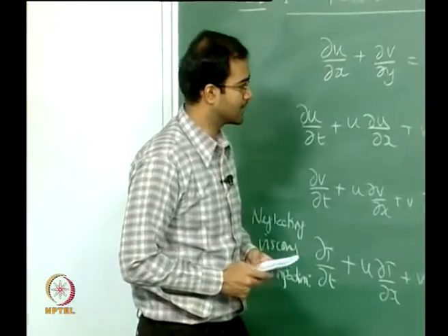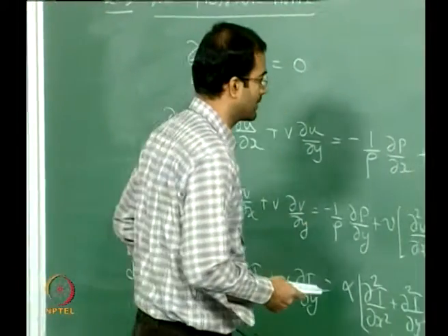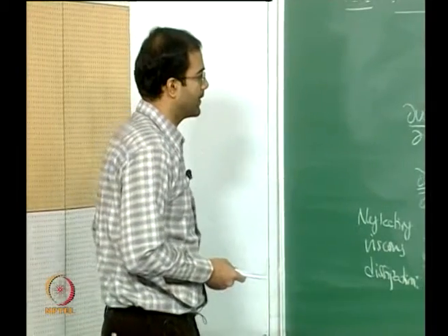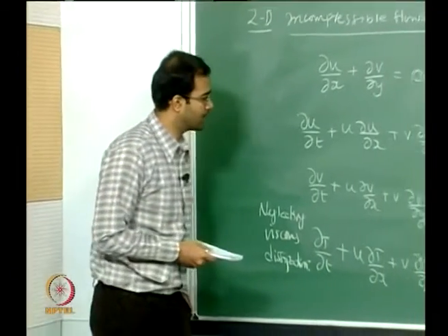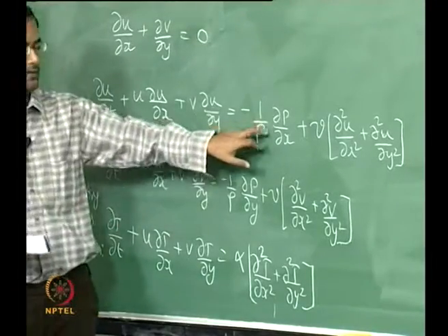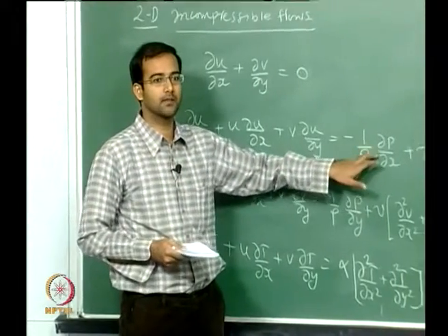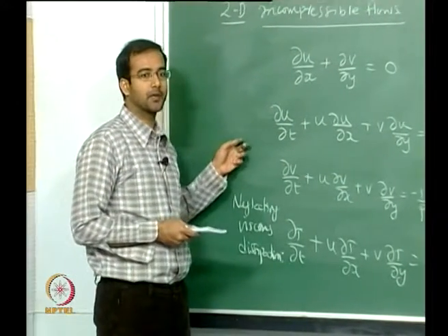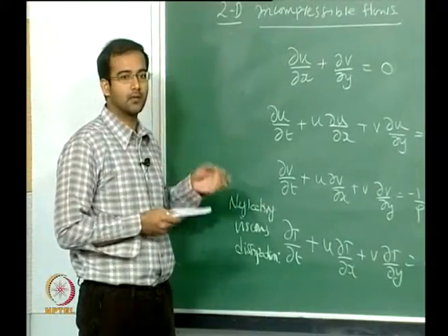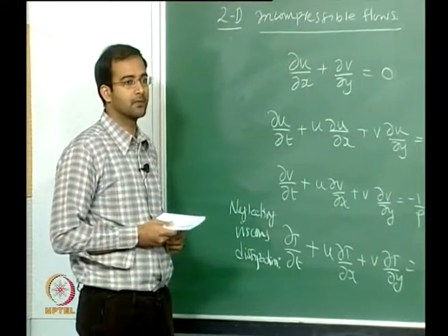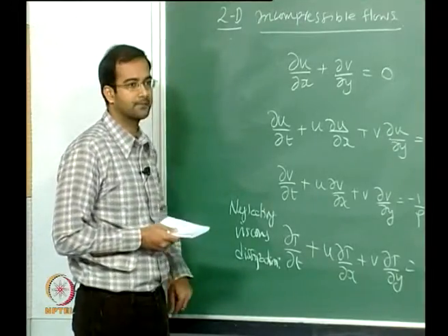Okay, so now this is more familiar to you. You have been working with these equations in your earlier courses. Now what we have to do, we have to think a little bit. See, there is a pressure term in the momentum equations, and we want to somehow eliminate it, because as you know, we don't have a separate equation for pressure, and when we want to numerically solve that, we want to simplify this problem. So how can we probably do that?